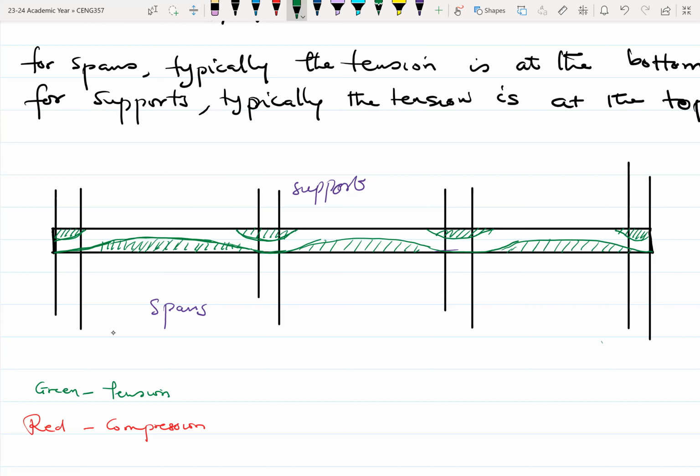All right. So basically your moment diagram, or the moments at supports, is bending upwards. Because it's bending upwards, the tension area will be the upper portion. Then the compression, so this will be the compression zone. This will be the compression zone.